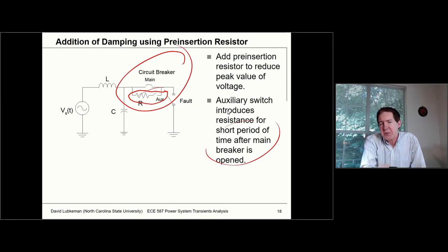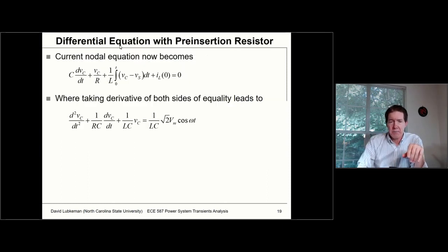The other thing you'll see in real life too is there will actually be resistance out there. I mean, there'll actually be some resistance in the source, and so in real life there's resistance out there which adds to the damping on the solution. So we wouldn't see the theoretical worst case, but it's hard sometimes to get a handle on exactly how much of that resistance is out there. So at least the worst case gives you a bound on what could be going on.